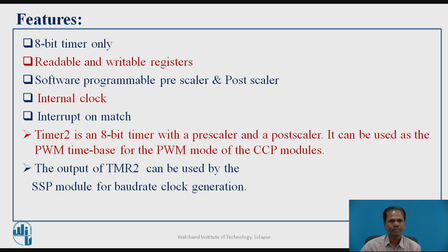Now let us begin with the features of timer 2 module of PIC microcontroller 16F877. So timer 2 is 8-bit timer only. It operates as only timer, not as a counter, and its count value is 8-bit.